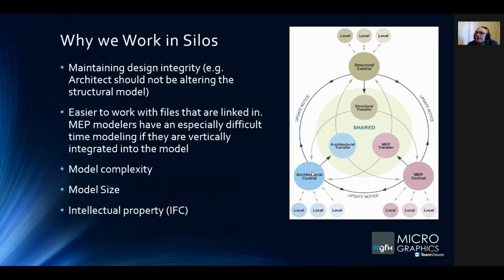And the reason for that is that the IFC model is non-editable. It has the solid elements that you've modeled, so the geometry of the model is there. The individual elements are accessible through a platform like Navisworks, or even within the common data environment itself, so you can read the properties, but at the same time nobody can edit it or save that block, save that component that you've modeled, or save that Revit family, whatever platform you're working in. They cannot save that into their own file and just reverse engineer it at the drop of a hat. They need to do a lot of work before they can get your intellectual property out of that model.